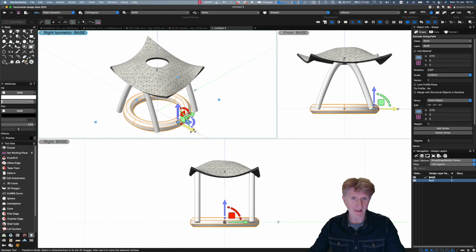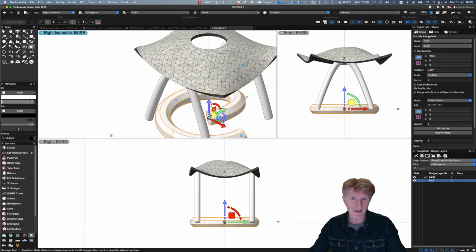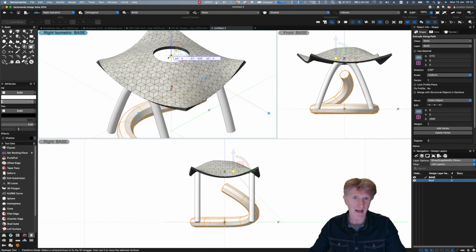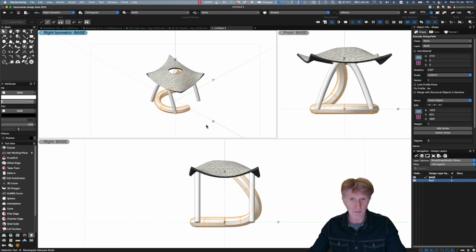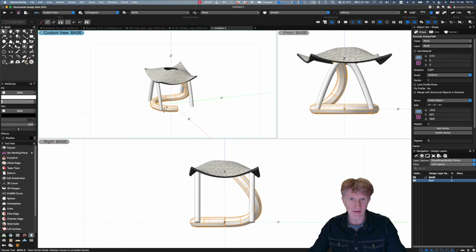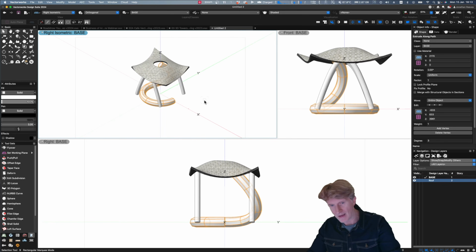Let's click on this vertex and we'll move it halfway, and you'll notice that if I wanted to snap, it's not actually snapping. So this time, let's click on this little yellow dot and you'll notice now it actually snaps. As well as that, I can click on the arrow, which is just freeform moving. Let's just freeform move. I can also click on the little vertex and snap up onto that axis to any other point. So that's pretty cool in that I've been able to three-dimensionally reshape this, what started as a circle, into a spiral.